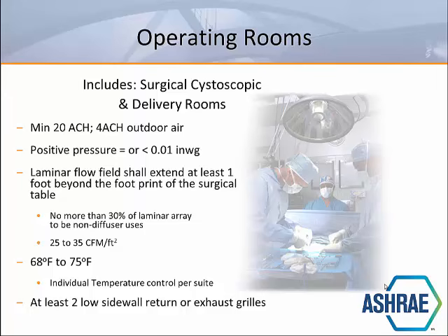Operating rooms should be positively pressurized to at least 1/100th of an inch. This is to minimize particle migration into the operating room. ASHRAE Research Project 1344, which was focused on pressurization strategies for clean rooms, recommends at least 2/100ths of an inch to minimize particle migration while doors are closed, and at least 4/100ths of an inch to minimize migration of particles when a door is in operation. As such, it is best practice to maintain a pressure differential of 0.04 inches to minimize particles from migrating into the operating room from the adjacent corridor.